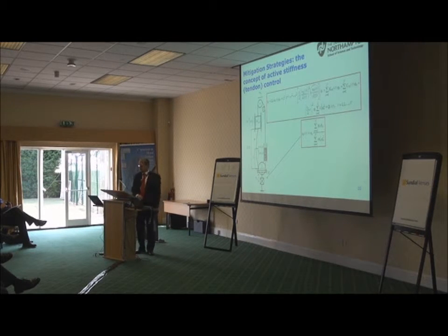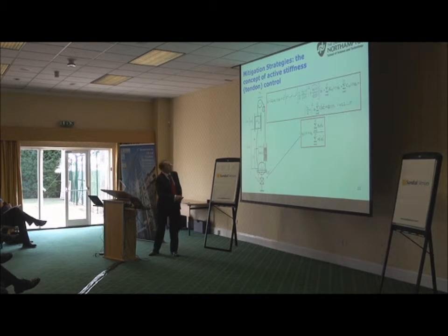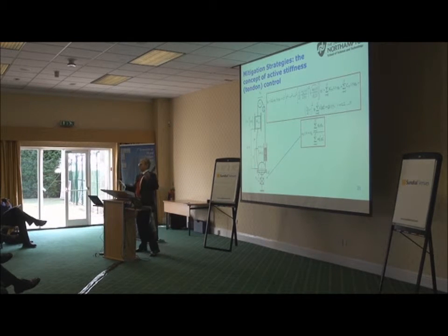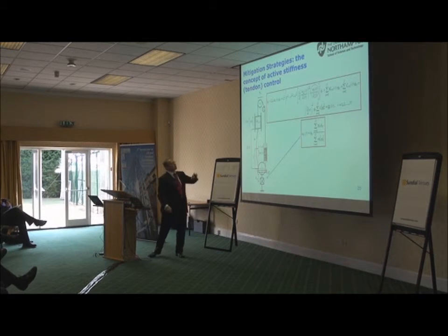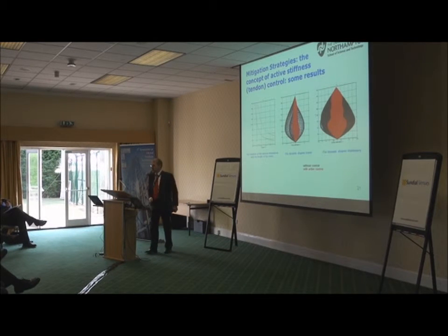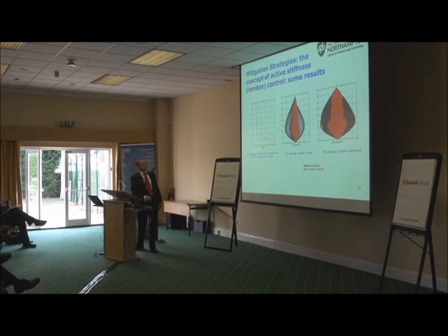Here's the mathematics of it. What is in this equation is the implementation of a feedback control. When we have motion here, it is informed by some input from the measurement of the response. We measure the response, we feed the measurement to a control algorithm, and the control algorithm applies this motion. And that way we damp vibrations.